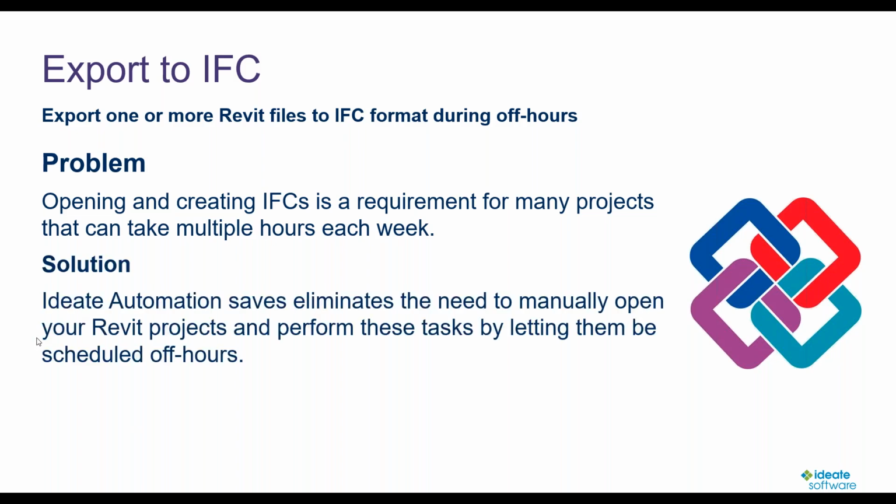With Ideate Automation, we are eliminating that need to manually open Revit projects yourself. These tasks can be performed by automation, and you can schedule them to run when you want, particularly off hours, which is obviously the most productive way of using this solution. You can set up these tasks to run at 5 o'clock in the morning, so when you come to work, the IFC files have been produced for you. You can just send them out, or do whatever you need to do with them.